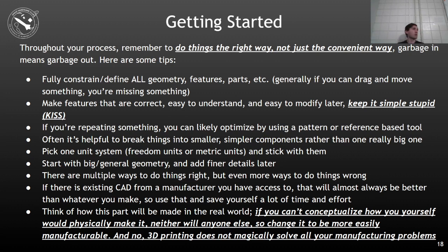That can happen, or like the CAD equivalent of that can happen if you try to change something later. So take it baby steps at a time. Everything is all kind of modular. There's kind of a whole timeline, like an ordered sequence, with a bunch of these features. You guys will see that later. Just make things easy to modify later. If y'all have heard of KISS, keep it simple, stupid.